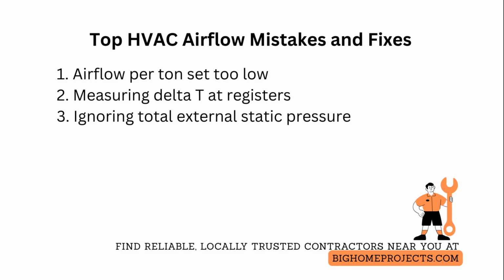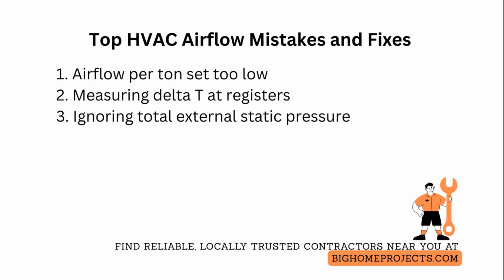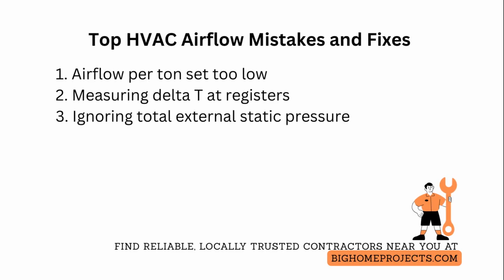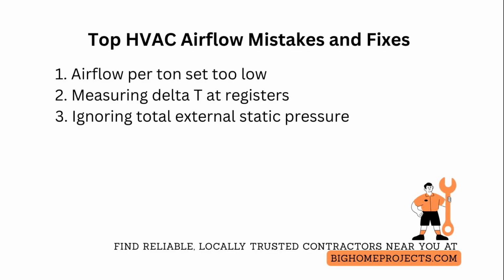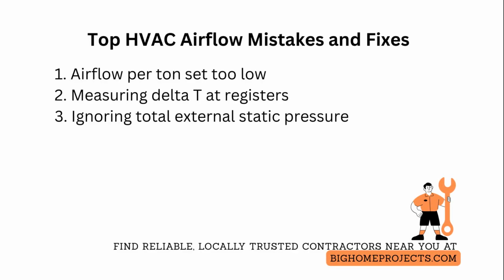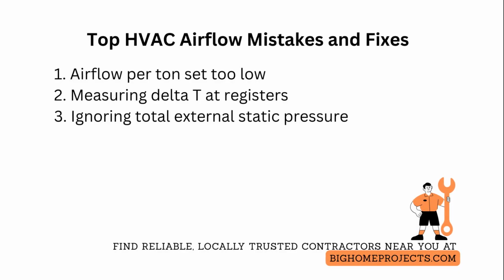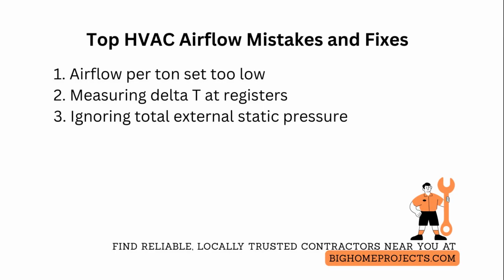radiant error. Another common issue is misreading the blower performance table by ignoring total external static pressure from a dirty filter, restrictive grill, or undersized return. Fix it by measuring static pressure with a manometer at the return and supply, cleaning or upsizing the filter to a larger media cabinet, adding return air pathways, and targeting a total external static pressure that keeps you on the blower curve where your selected speed actually delivers the desired cubic feet per minute.